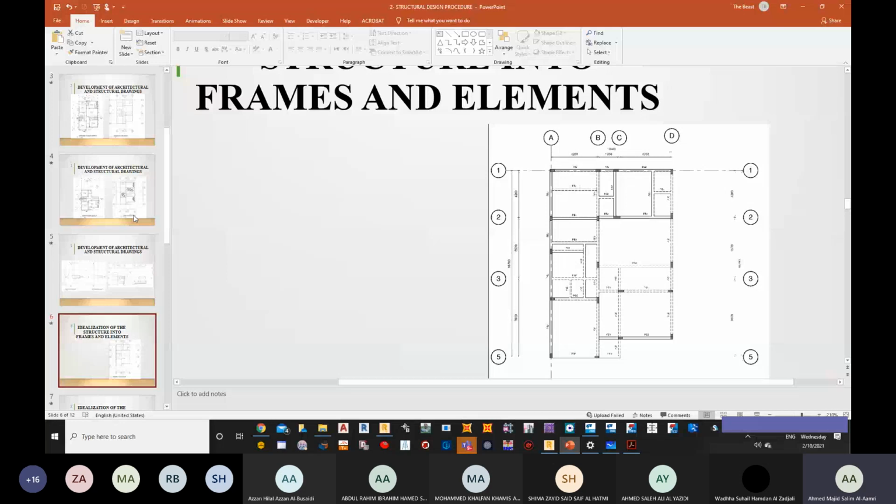We draw our free body diagram to make the analysis simpler, right? We are trying to reduce any 3D things to 2D, which are simple to understand. Now, when it comes to structural software, the drawings are already available in 3D and the software analyzes it as 3D, so you don't need to draw the free body diagram once again. Are we clear? But when it comes to manual design or manual analysis, as we are going to do in this particular course, it's very important for you to know how to idealize.